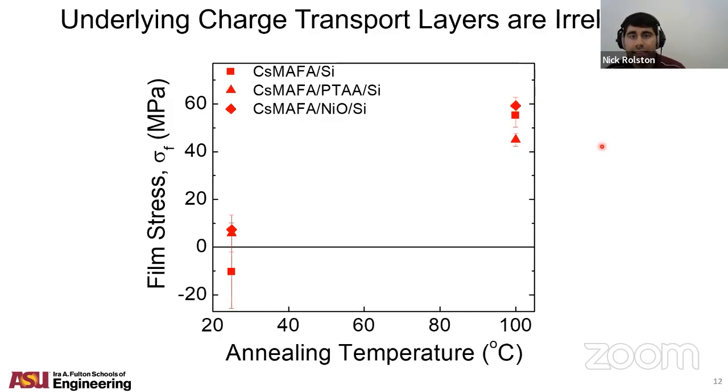And so this is just an important indication that because we're not dealing with epitaxial growth situations or lattice matching between layers, the contribution of thermal expansion from any other layers, either underlying or overlying transport layers, should not have an effect compared to the substrate. The substrate should dominate the residual stresses that form after processing.